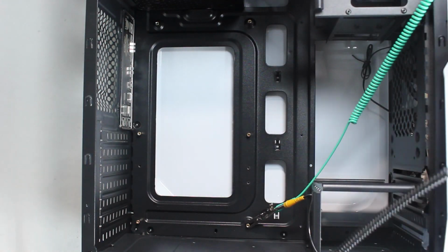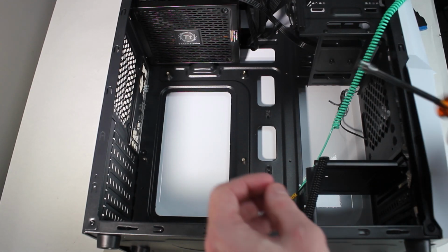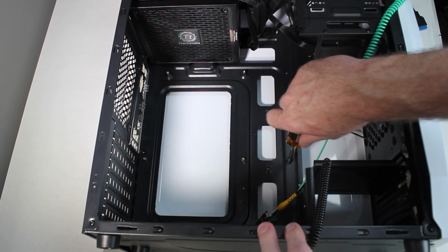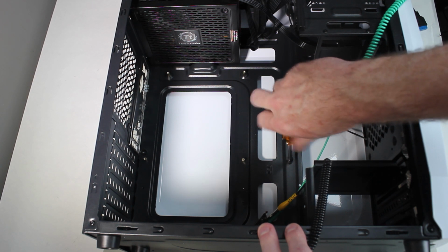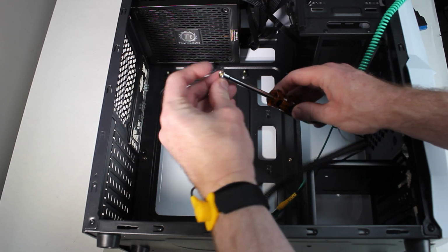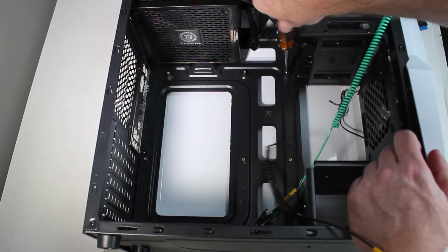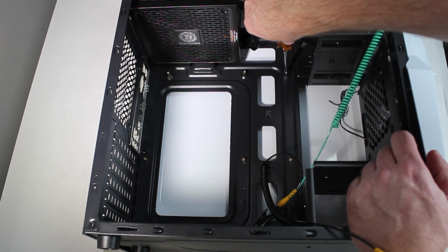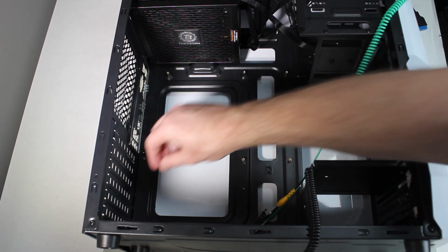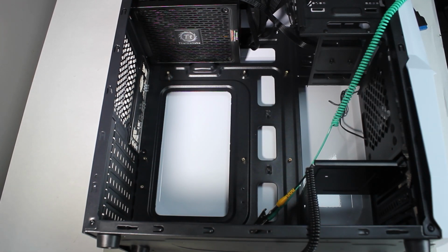To install the standoffs, a nut driver can be used, which is found in most computer toolkits. It is just a matter of putting the standoff in the nut driver and then screwing the standoff in. When screwing the standoff in, like all the other screws in the computer, they are pre-threaded. You only need to screw it in until it is finger tight. When you feel it has got to the end of thread, stop screwing it in. If you attempt to screw it in any harder, you risk damaging the thread. Also remember, you may want to get the standoff out again one day, so you don't want it in too tight. If you don't have the nut driver, you can just screw the standoffs in by hand, and again, just screw them in until they are finger tight.